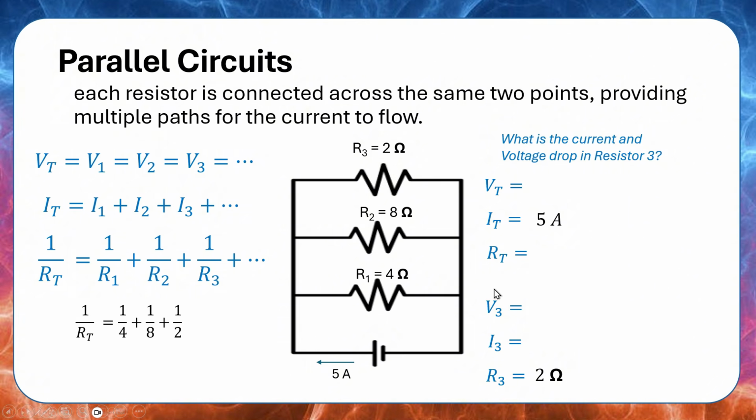So solve them using this. And look at this. Which of the resistors here has the smallest resistance? It's the R3. And we're going to expect that the R total must be smaller than the smallest amount of resistance in our circuit. So it should be smaller than 2. So let's try if it is true.